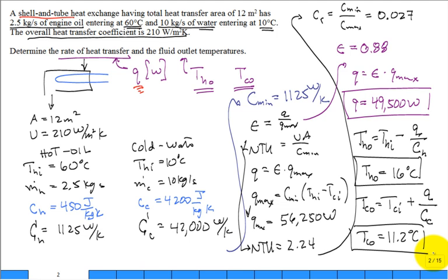Somebody says make some adjustment to the heat exchanger, either flow rate. Which flow rate would you change, and would you increase it or decrease it? The cold, it's going way too fast, isn't it? You could slow it down some. It'd probably do the same job of having a similar Q. Oh, it'd reduce it a little bit, but not much, right? Because you could see that it's not picking up much heat in the cold. Anyway, little observations like that.